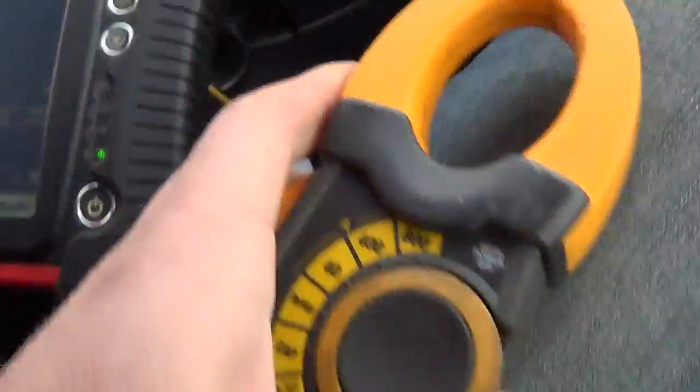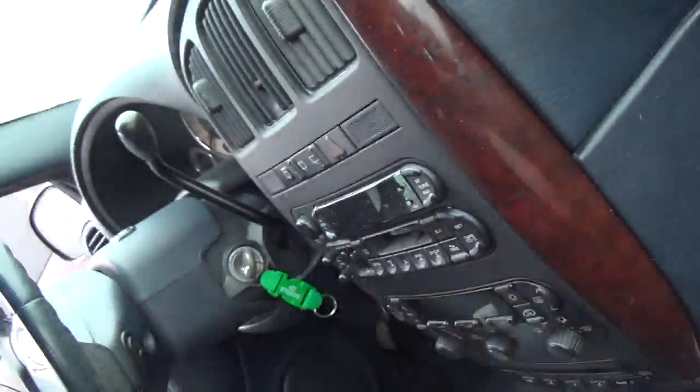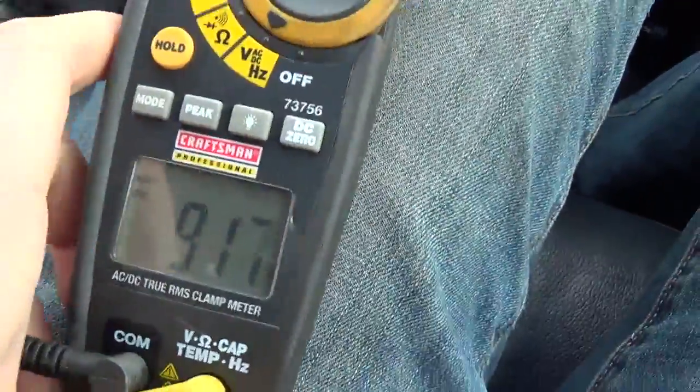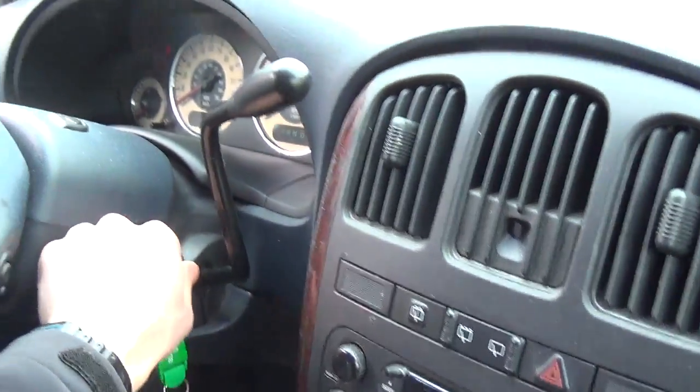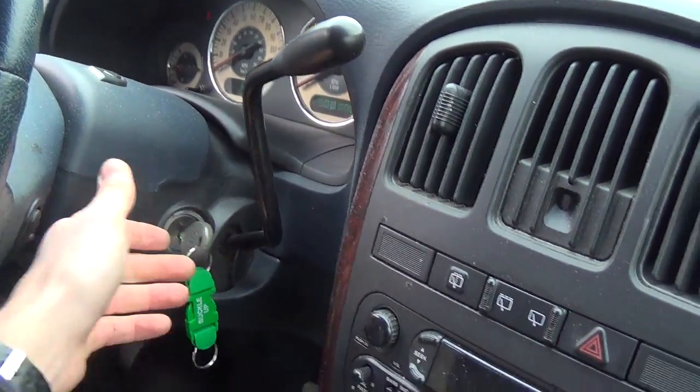Our test light is getting kind of dim. Let me just verify the voltage with my voltmeter. So I just unplug the leads from our Verus. Let's see, plug them in here. 9.2. So the Verus calibration's off, like you saw in a previous video, or maybe you haven't. But anyways, battery's dead. We need a jump pack on this thing, or start it up and let it charge up, because we can't really do definitive testing with the battery drained.